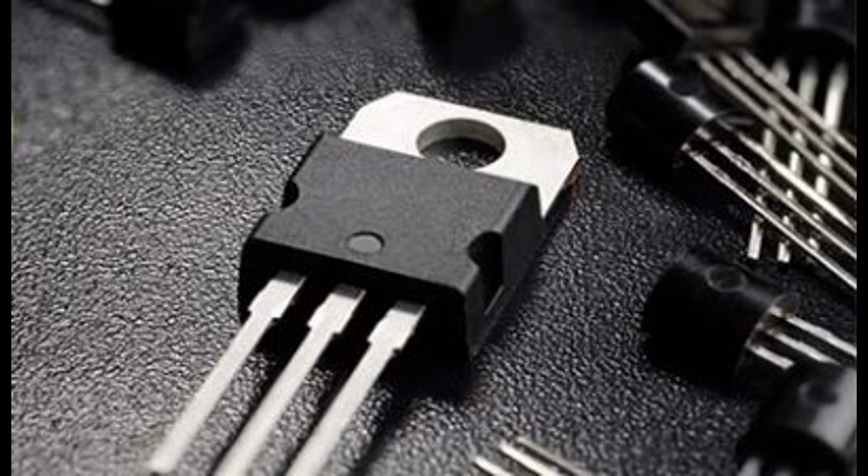Surface and thermal management. Power MOSFETs often have features to enhance heat dissipation, such as heat sinks or improved packaging designs to maintain reliability during operation. Doping profile. The doping concentration and profiles of the source, drain, and channel regions are critical for optimizing performance characteristics like switching speed and on-resistance.